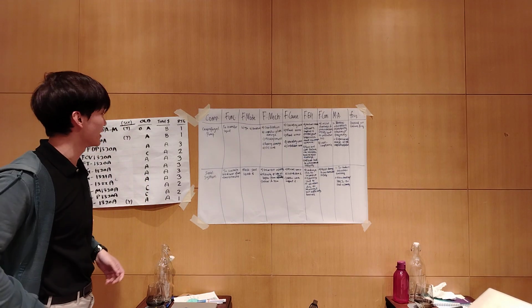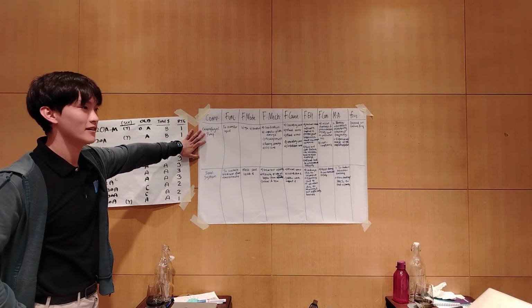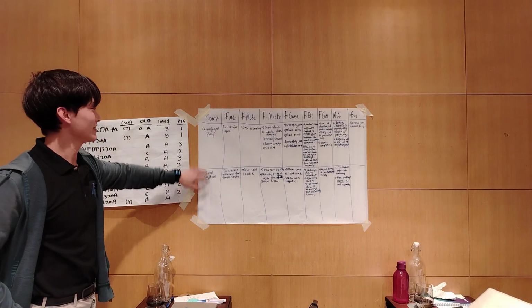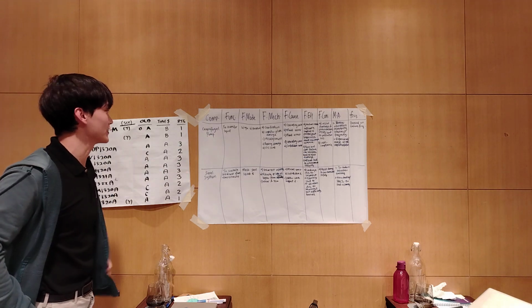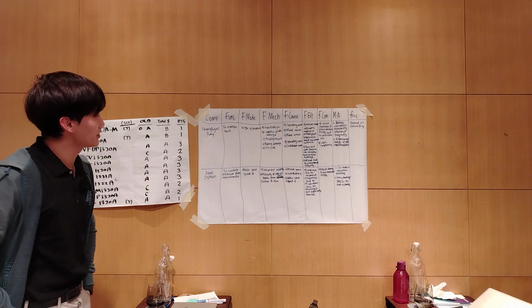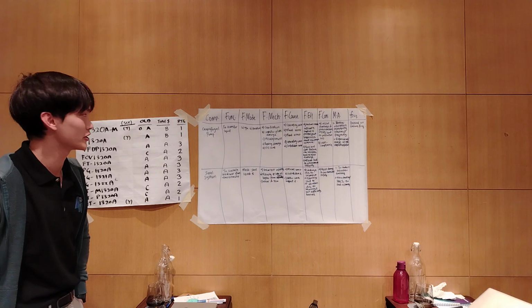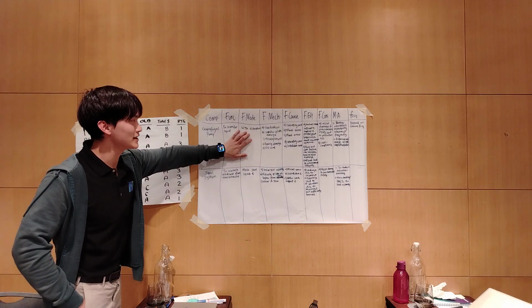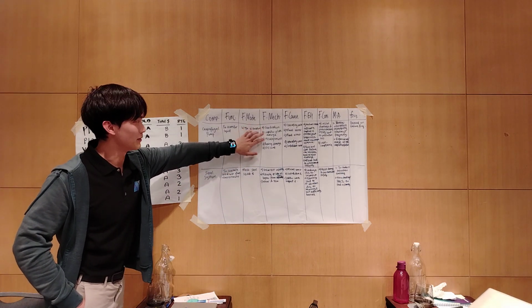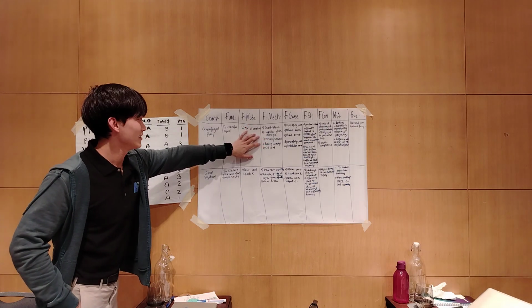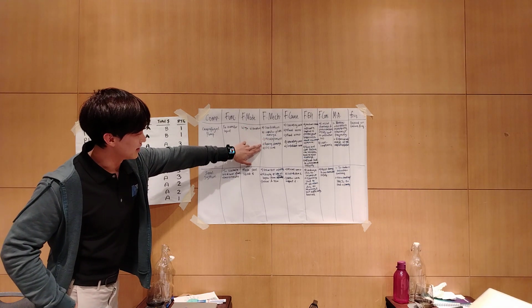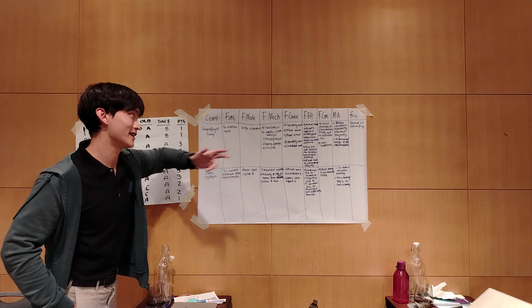Okay, so similarly we have two components: the centrifugal pump and the seal system. The function of the centrifugal pump is of course to transfer liquid. So the failure mode that we can detect is high vibration. The possible causes leading to this are, first, cavitation. Number two, impeller plate damage, FOD. Third is misalignment. Next is bearing damage or oil leak.